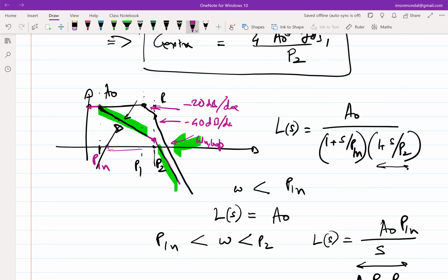When you didn't have the extra C, it wouldn't have looked like an integrator-like response. We also proved using our underdamped equations that this condition leads to zeta being much less than 1, so you will have a lot of ringing.